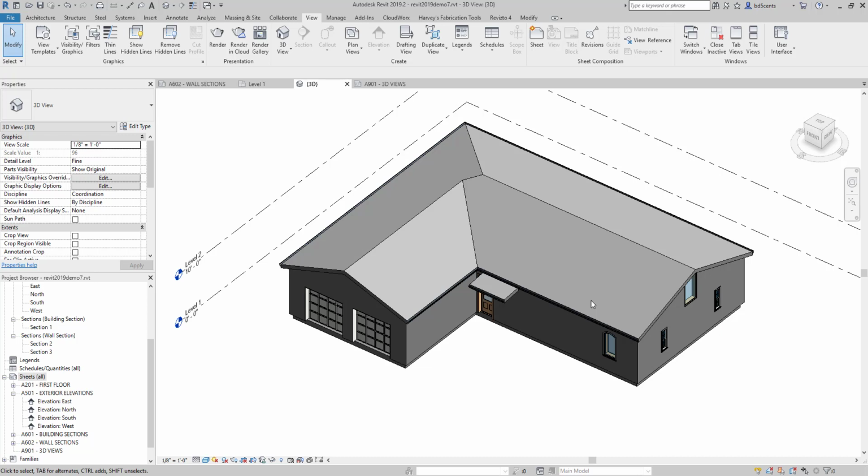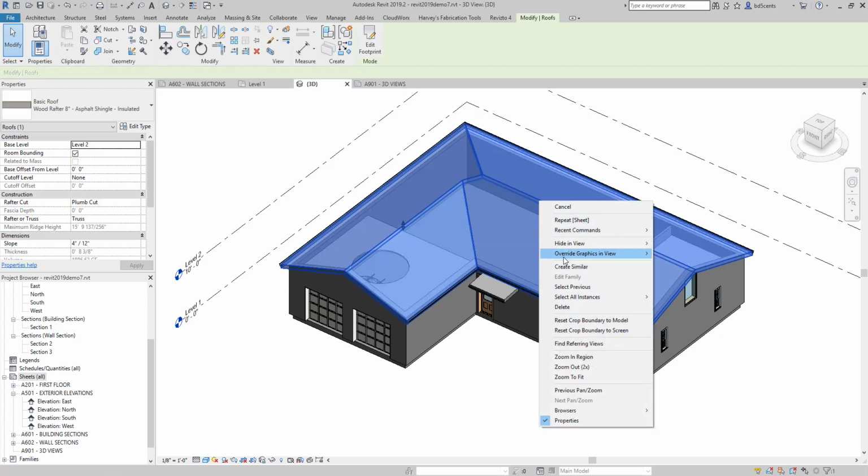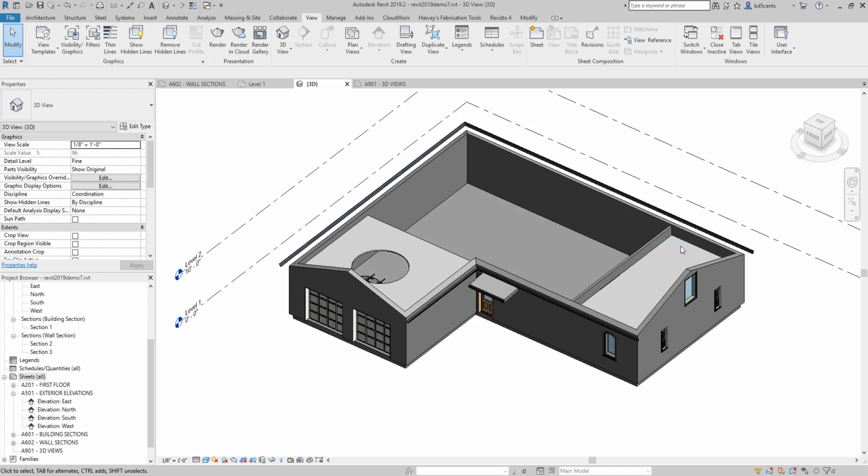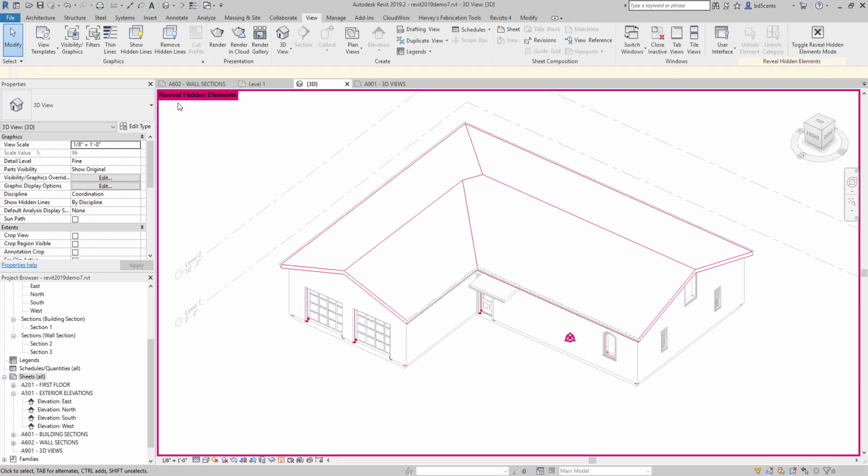Hiding an object permanently: let's say you want to hide some of the same roof sections in the 3D view so that you can see the ceilings below it, but not all the roofs. You can select the roof, right click, Hide in View, Elements, and then down below you'll notice the light bulb. The light bulb reveals the hidden elements. So see the red box? All red objects are hidden in this view. The analytical nodes, you can leave them alone. That's what these are down below.